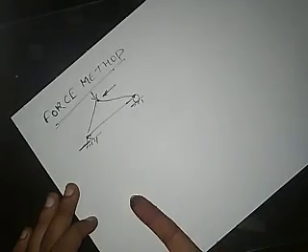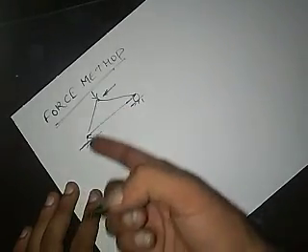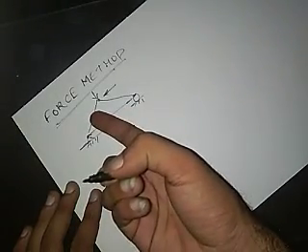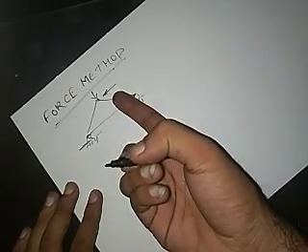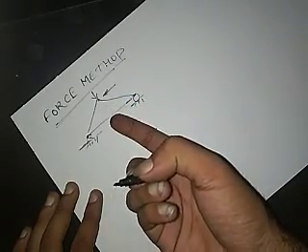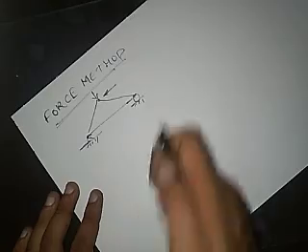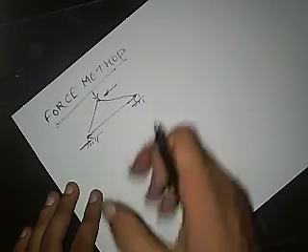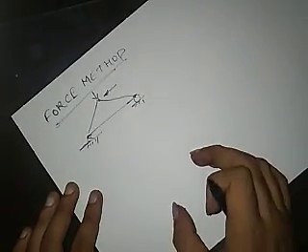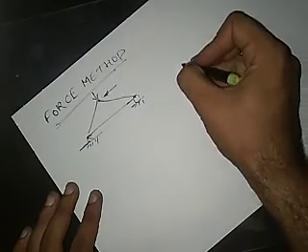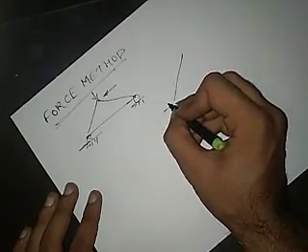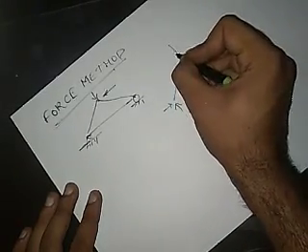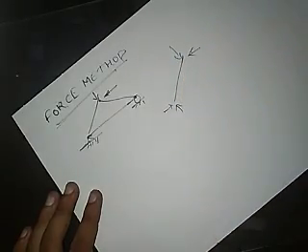In order to get the amount of deformation in it, I will need to know the support reactions first, so that I can make a free body diagram and calculate the amount of force acting on that particular member.